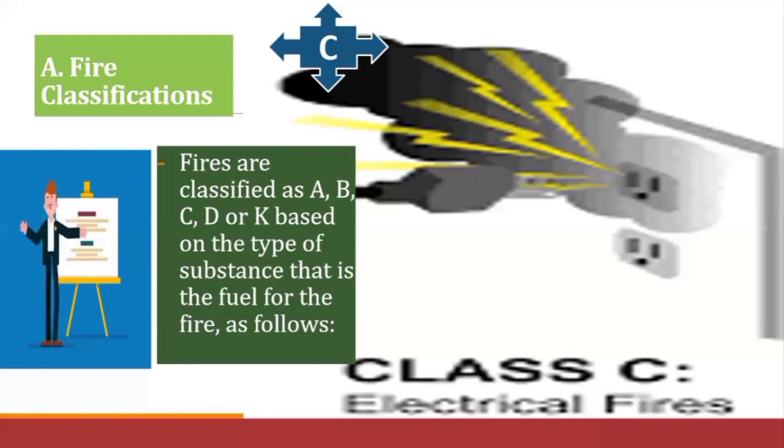You can switch it down, you have to pull it down and make sure that there is no electricity or current. Do not make use of other extinguishers that may serve as a good conductor of electricity. Otherwise, you or others may be electrocuted, or there is a possibility of unwanted effects.